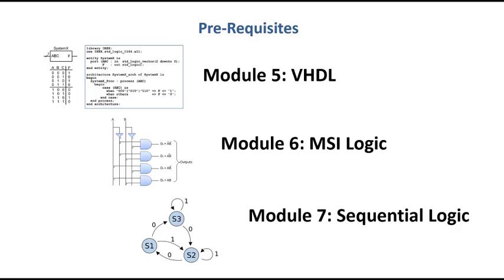Storage is not, in this context, memory arrays, so things like DRAM in your computer. What we used was a D flip-flop. A D flip-flop was a very fast storage device that could store 1 bit at a time, and it would only grab the input and store it upon a triggering event. The triggering event that we used was the rising edge of a clock. So you should have all of that knowledge in your past, or you should at least know roughly what I'm talking about before taking this class.